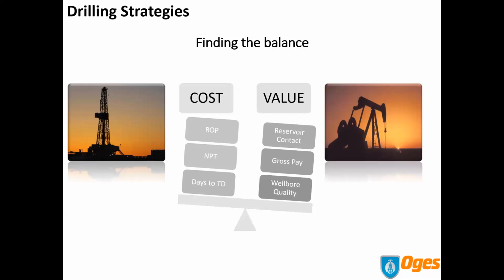So one of the main goals of drilling optimization is to reduce the total time, essentially maintaining the risks. Obviously, HSE is still foremost in everyone's mind, but maintaining the risk as low as possible. And one way to achieve it is through a selection of optimum drilling parameters prior to a run, selecting the suitable drill bit, drilling fluid type. Another approach relies on real-time analysis in order to optimize the operational parameters, such as bit weight and rotary speed